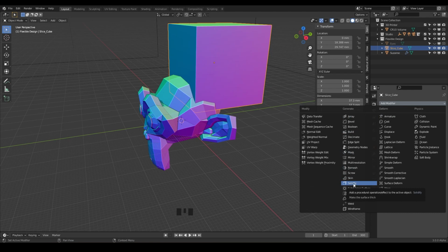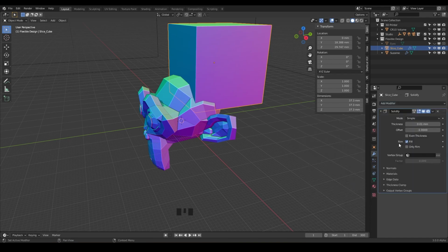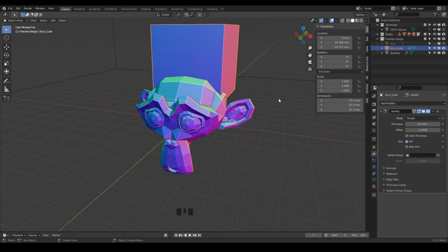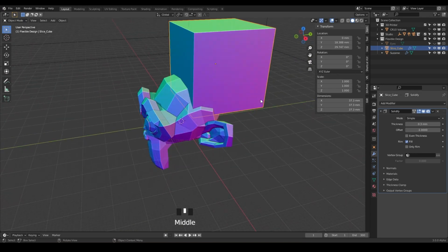So if you remember anything today, it is to make sure if you are slicing, the solidify modifier is going to be your friend. So let's go ahead and do that. And just like we did in the last lesson, we'll do 0.3. You can do 0.5 if your printer's not as dialed in as it should be. So now we've got a box here.